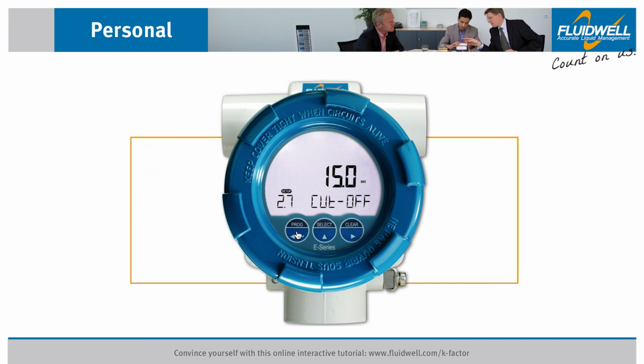Hold Prog for 3 seconds to exit the Setup menu and return to Run mode. You can see the configured settings in the main display. You have now configured 2 different K-factors for simultaneous volumetric and mass flow measurement on the e-series.